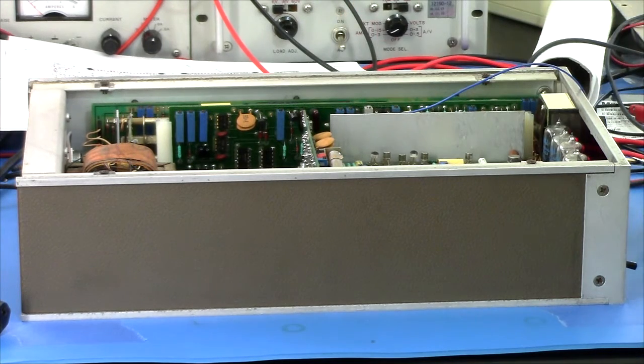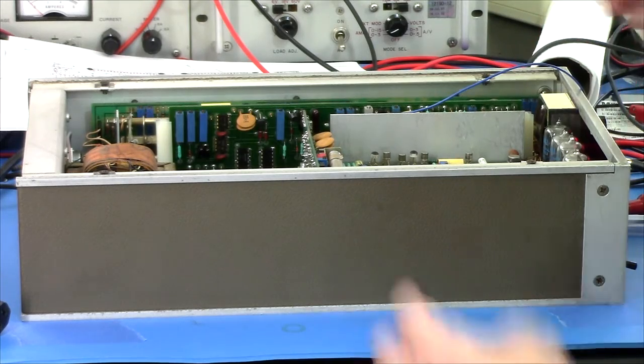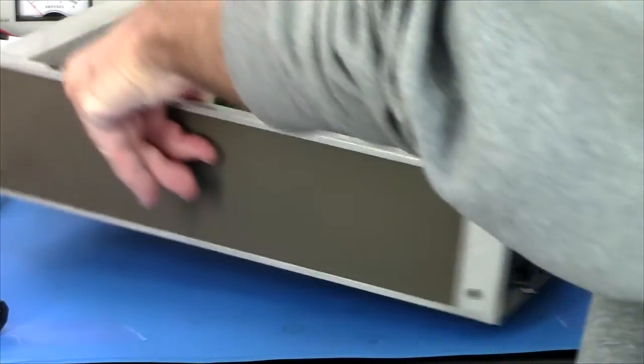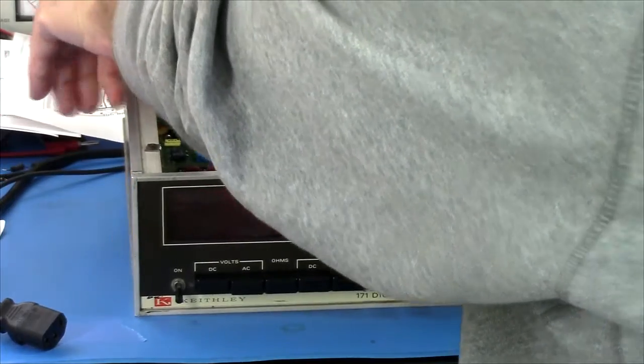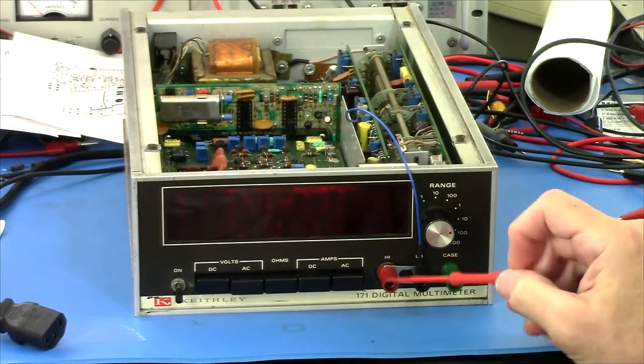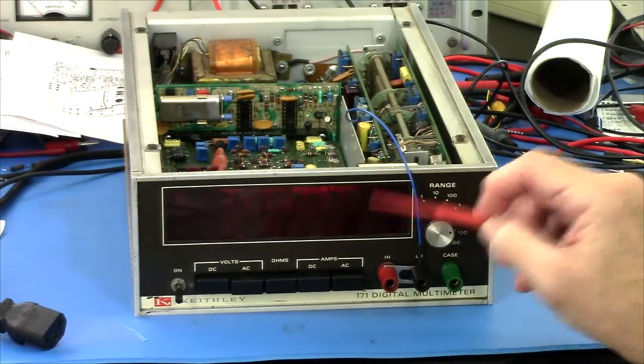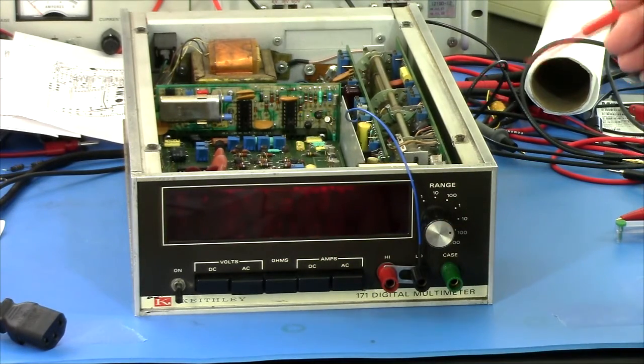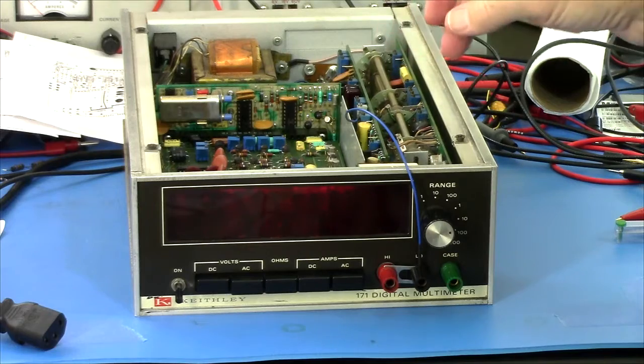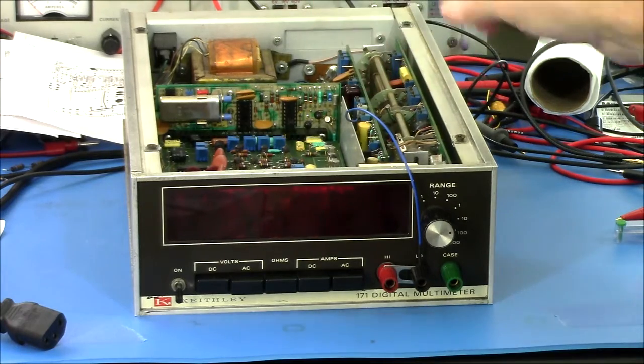So that's what's going in there. I will replace it with a new one. But then I have this jumper, and it comes over here, connected to ground. Okay, and again the input is shorted to ground, so I should be reading 0, if everything's working right, even with that op amp in place.